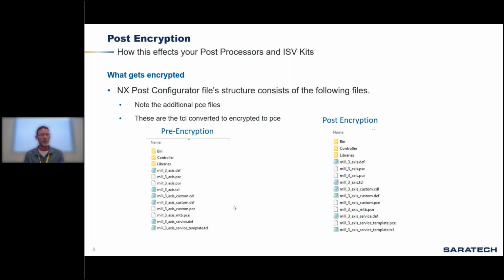So then you take the TCL code files out, send that to the customer, and that is an encrypted file. It's just the coding behind how the tool data was pulled out of and put into the header of your post processor, or the way that we made NX work with probing and grab the data and do closed loop machining. That is all proprietary to companies, and they want to work very hard at protecting how they came to that conclusion.